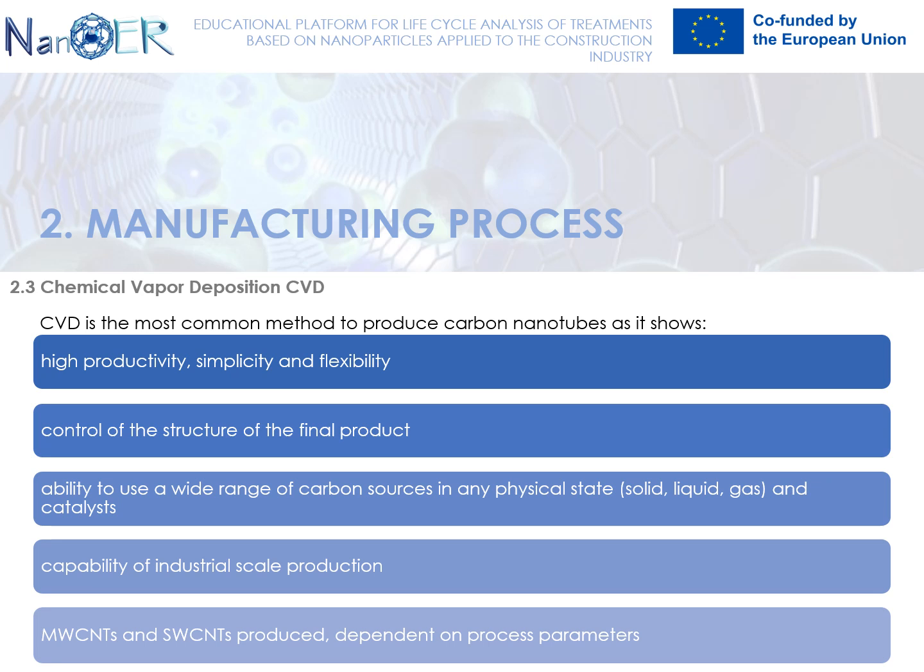The CVD process shows lots of advantages in comparison to arc discharge and laser ablation. These are the following. The CVD is simple and flexible. The reaction process is easy to control and the reactor design is uncomplicated. The structure of the final product can be easily controlled. The carbon sources used are available in high quantities as raw materials. There is also the capability of industrial scale production. The CVD offers variation of the produced materials, for example, the size and type.